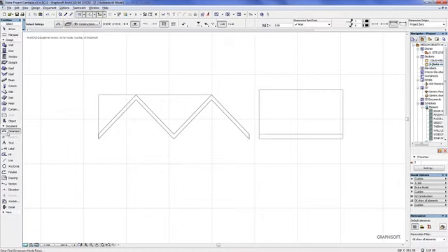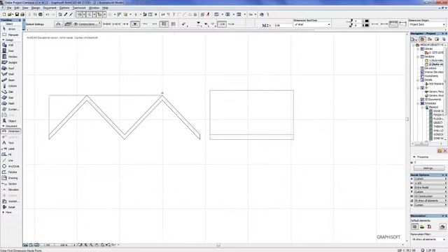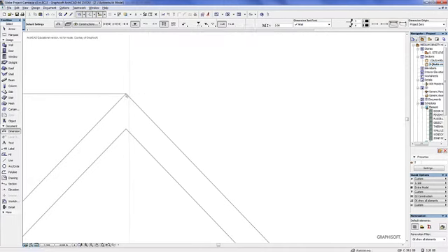So click to select the dimension in the toolbox. Then go to this construction method, which is the RL, relative level dimension, and then click twice on the point. Sorry, 3 times. So 1, 2, 3, and then come out to, oh, it's not letting me do it. Hang on. Okay, so you need to do 2 clicks and then pull out, and then the hammer comes up, and then you click the 3rd time.